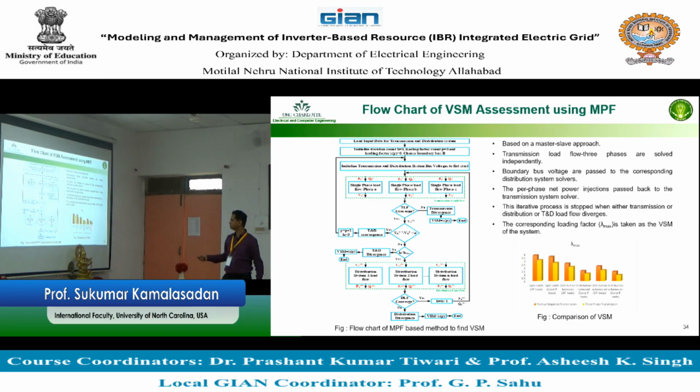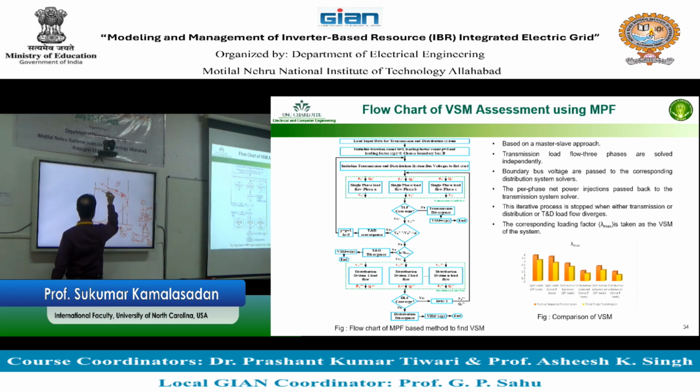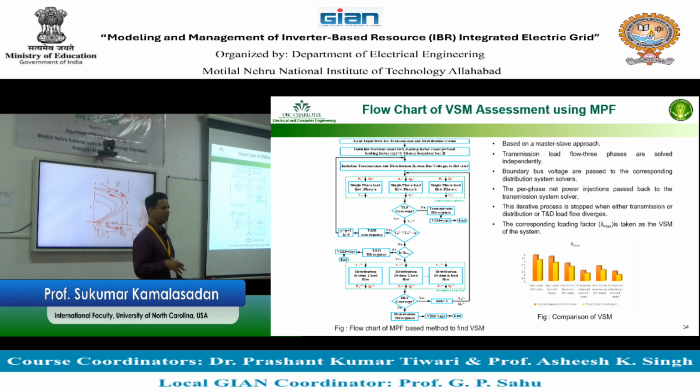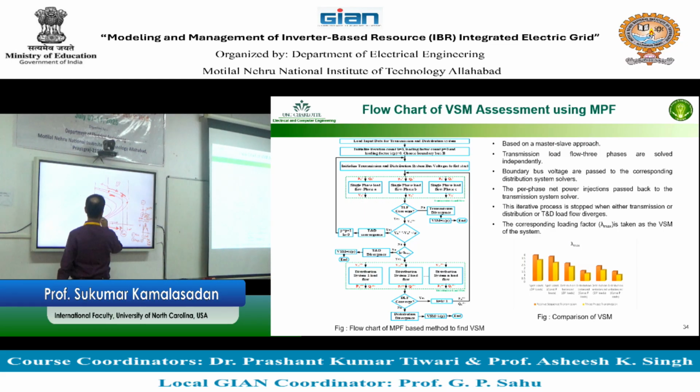So if you look at distribution system unbalanced with constant P, you see this voltage margin is very low. Now this curve, what you see on that bus when the DER is connected. In the classical stability course when we teach, this kind of curve will only come when there is a power factor change or capacitor connected load and things like that. This is called multiple PV, and there will be a stability margin line that you plot.